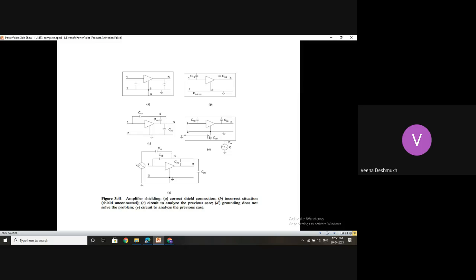They should always have proper connection. Thinking that small values may not have any effect on the final output is not right. These capacitors, if kept open, produce voltages with another conductor here. They form the capacitance with another conductor over here if not grounded properly.